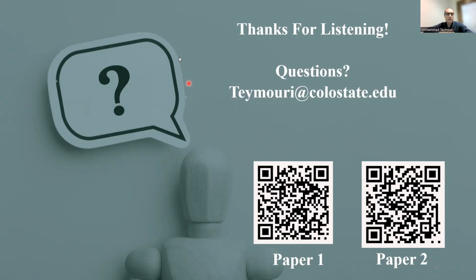For example, I have a suggestion for you. If you have the samples with what you want to make, you can cast a concrete sample, drill a hole in it, for example 1 inch or 2 inch, and put some water inside for a couple of days. You make sure that you cap the hole and everything. After, for example, 3 or 4 days, if you have a pH meter or a pH strip, you can measure the pH of the water inside that hole. It can give you some idea about the pH of the low clinker mixes compared to the OPC.